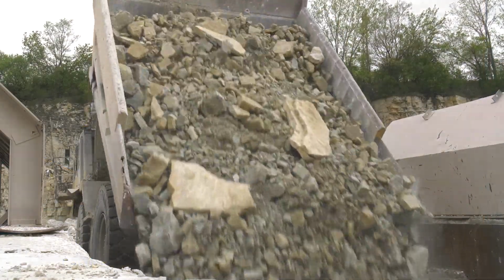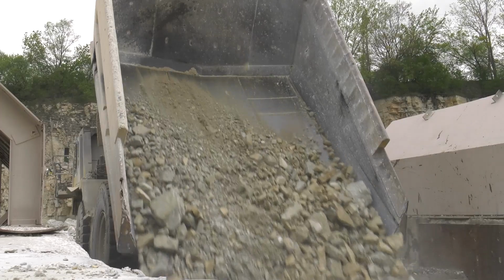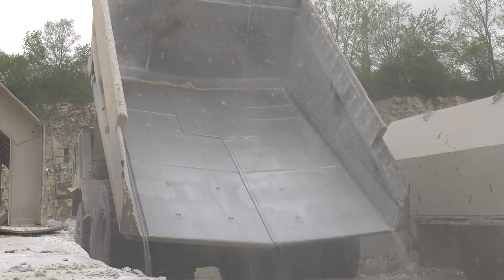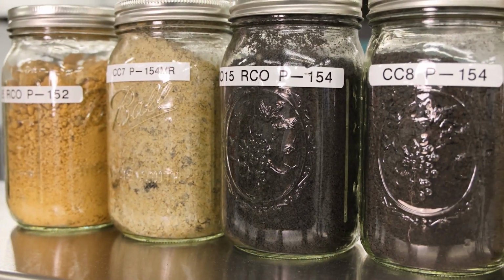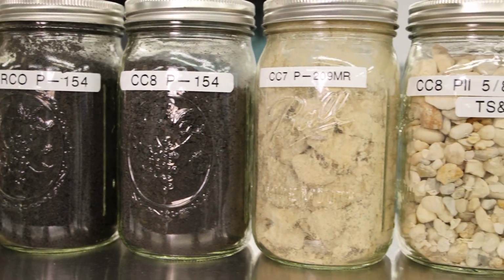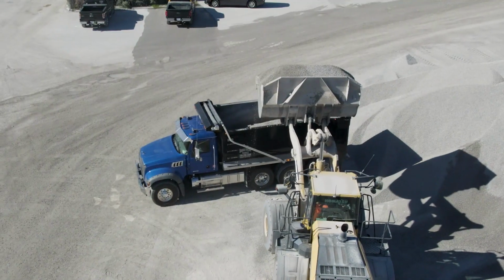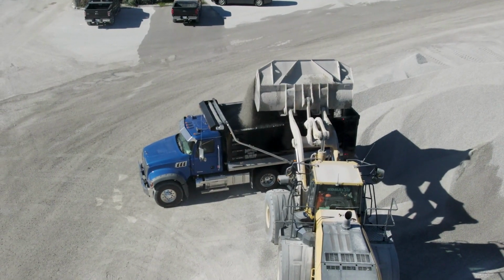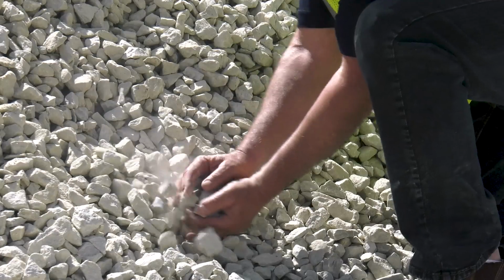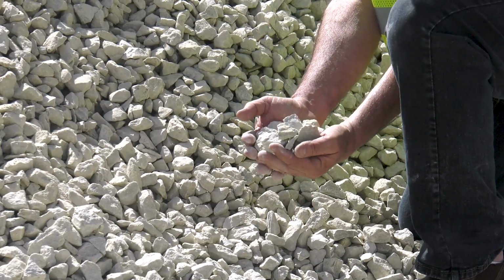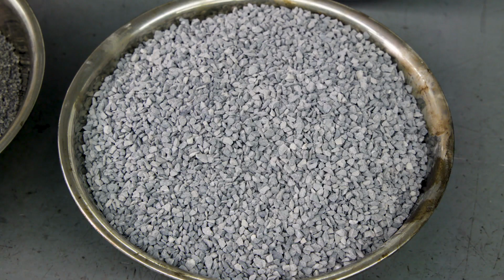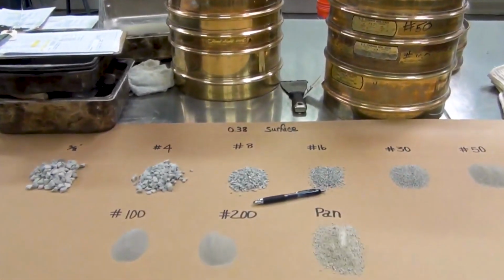Aggregate typically consists of crushed or natural stone and sand, and sometimes mineral filler. The type of aggregate and the distribution of particle sizes, or gradation, affect pavement constructability and performance. Specifications may vary for aggregate sizes. The FAA defines coarse aggregate as material retained on a number 4 sieve with no particles over 1 inch. Fine aggregate passes through the number 4 sieve.